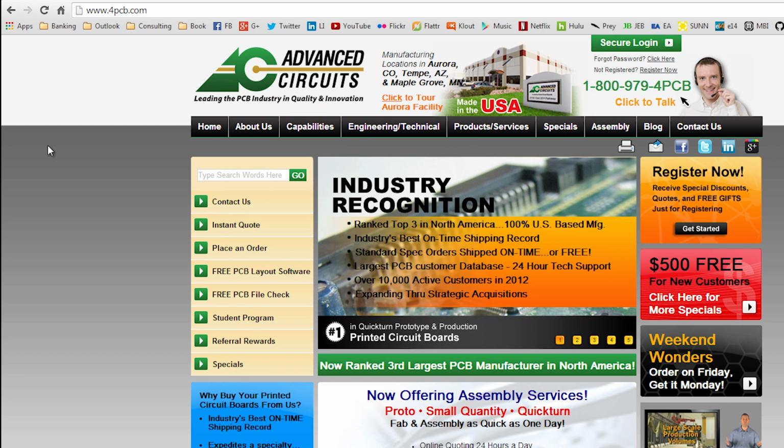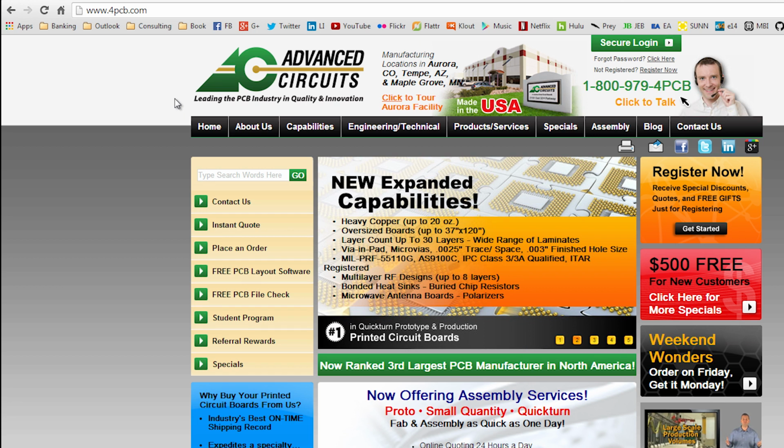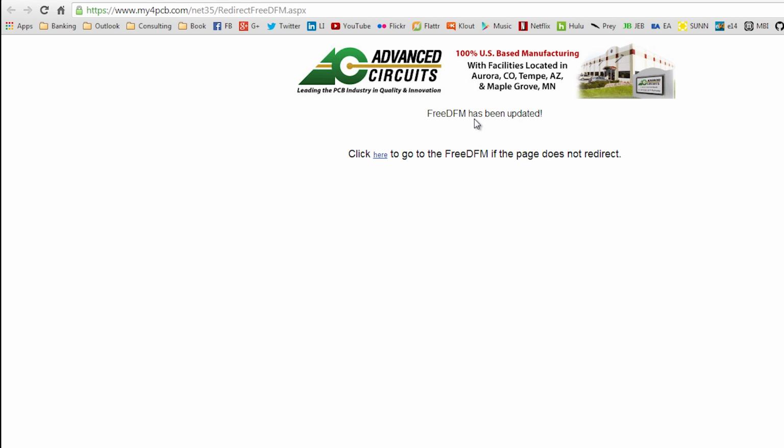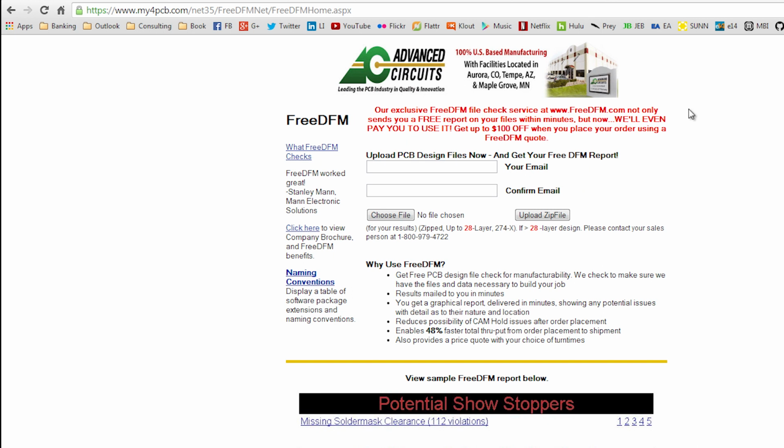Okay, so Advanced Circuits is just an example of one of many PCB manufacturers. We can click here to basically get a quote, but you can see that they have free PCB file checks. They call it free DFM. This is usually a good idea just to make sure that you're abiding by all of the rules of your appropriate manufacturer. So you just put in your email address.